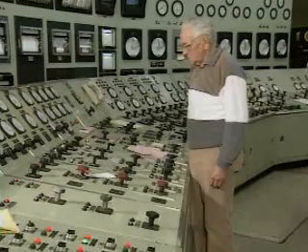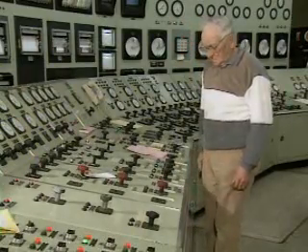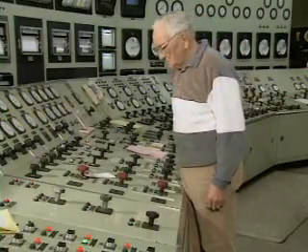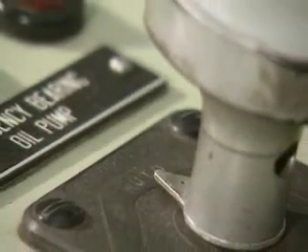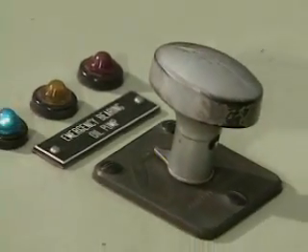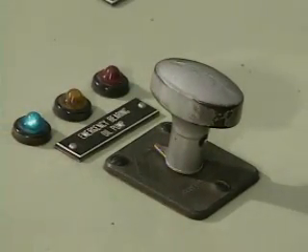The turbine lube oil system is vital to the operation of the turbine. So in this part, we'll discuss some operator responsibilities that are intended to keep the lube oil system functioning properly. It's important to make sure that the controllers for the standby oil pumps are in the standby or automatic position. If a standby pump is not in the standby or automatic position, it will not start automatically when it's needed. If the pumps fail to start, the bearings may not receive lubrication and damage could occur.